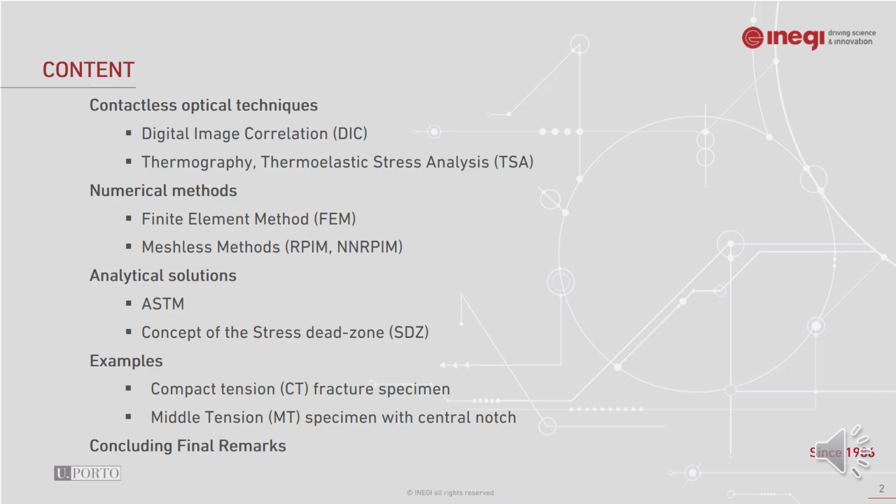So this work includes some information regarding the contactless optical techniques resorting to the digital image correlation and thermoelastic stress analysis. In terms of the numerical methods, finite element method and the meshless methods, which are RPIM and NNRPIM, are considered. Analytical solutions are related to the ASTM standard and the concept of the stress-state zone.